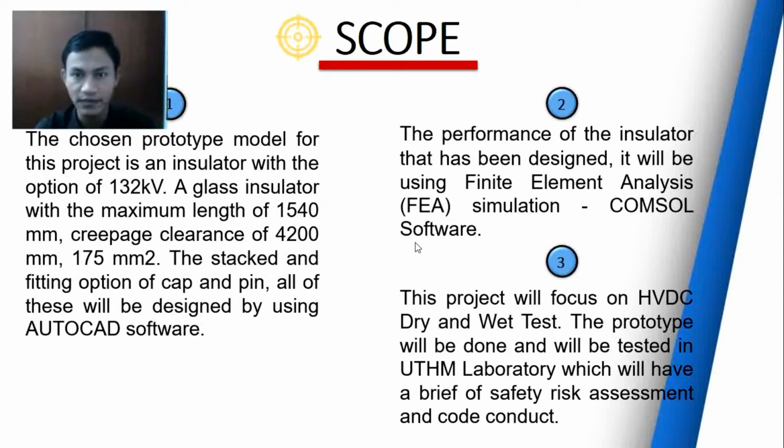Next is the performance of the insulator that has been designed, using finite element FEA simulation software. And the last one is the project will focus on HVDC dry and wet test. The prototype will be done and will be tested in the high voltage laboratory, which will have a brief on safety, risk assessment, and code of conduct. So that's all for me.